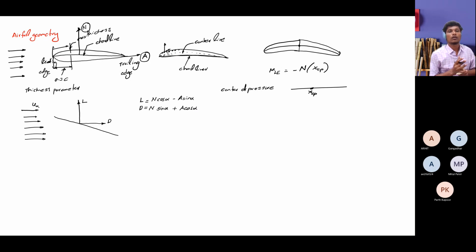So if you integrate all these lift and drag forces at every point, you will get one resultant vector. That is what we generally call the resultant vector. We always need to recall what our resultant vector is. The resultant vector is obtained by integrating all the forces on the top and bottom surface of the airfoil, and then taking a summation of it, you can find the resultant vector and its position. Once you get the resultant vector, from there you can resolve lift and drag forces.